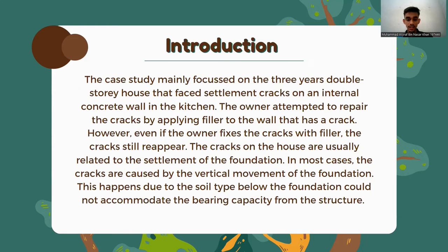The cracks on a house are usually related to the settlement of the foundation. In most cases, the cracks are caused by the vertical movement of the foundation. This happens because the soil type below the foundation cannot accommodate the bearing capacity from the structure.